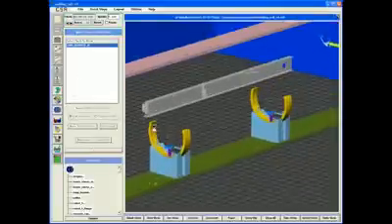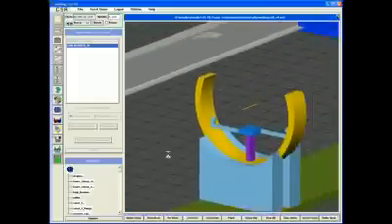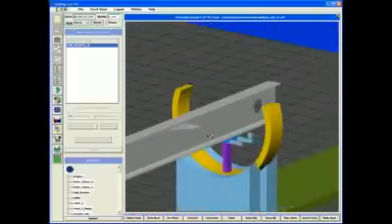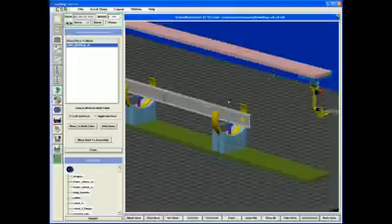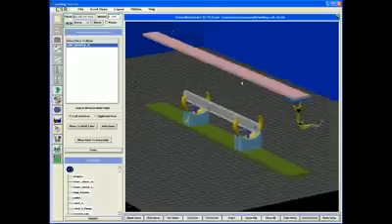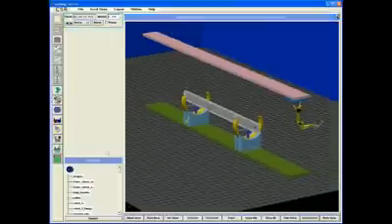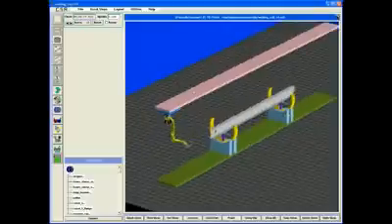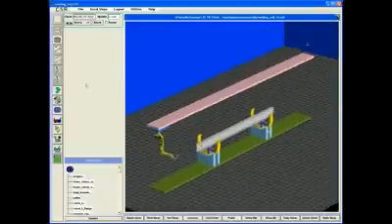When I say move to weld table, you can see we place it in position. We drop it down in place, and then we clamp the members so that when the assembly rotates, you've got a firm hold on it. All that's left now is to create the program and run a simulation.